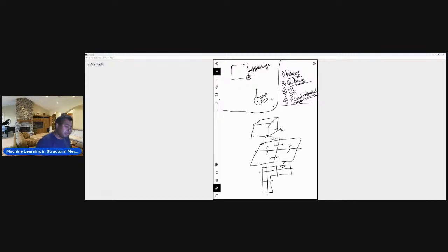That chunk of the element could have that elastic property, whereas the other chunk could have a nonlinear constitutive law in it. And then we can look at, for example in terms of crystal plasticity, how that deviation would occur in terms of either an unassembled element or a pre-assembled chunk of elements, so to speak.